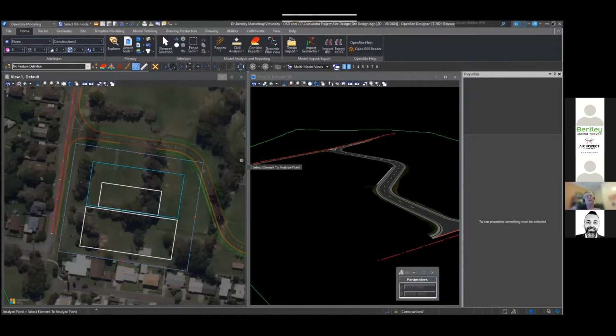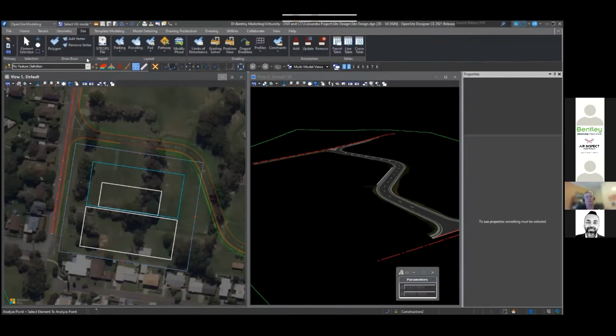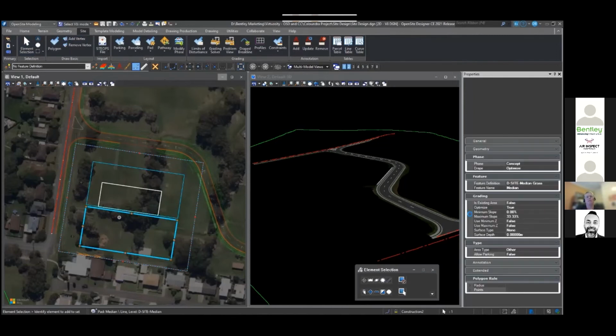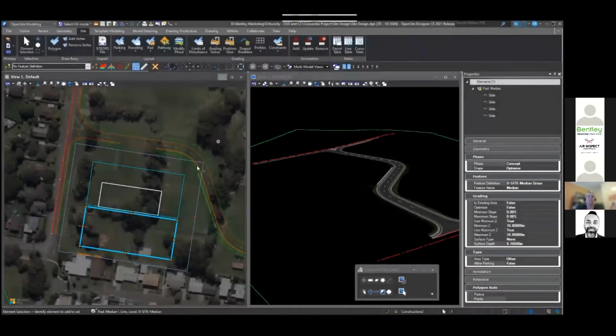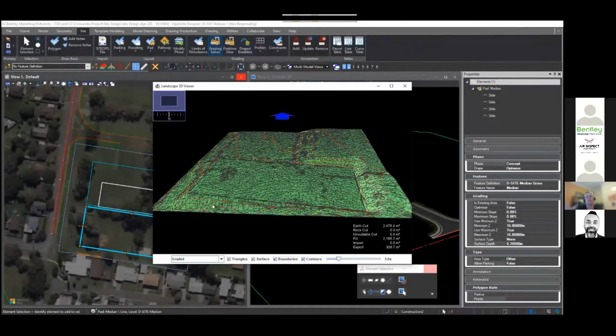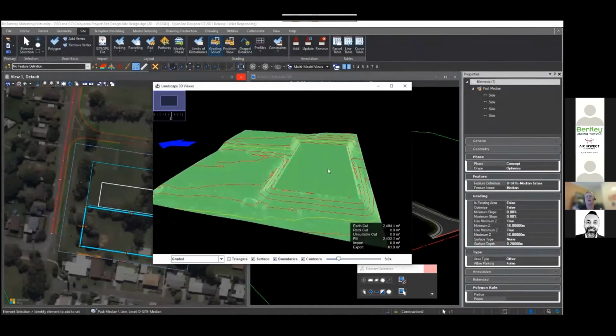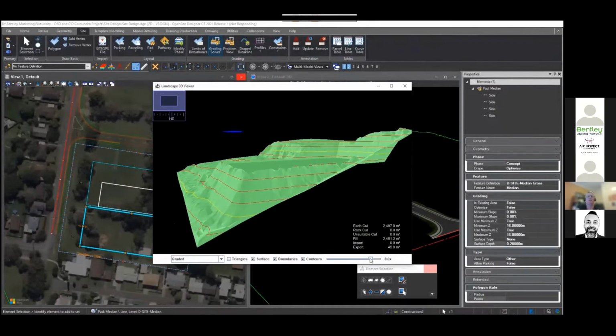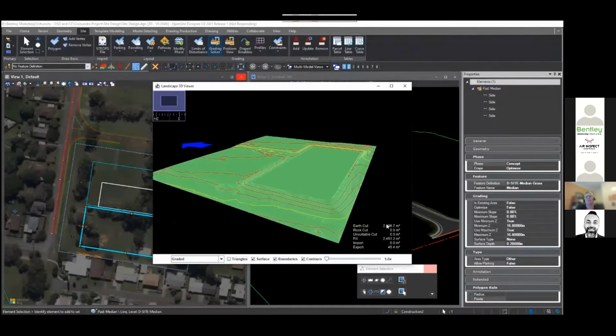So the first thing that I'm going to do is the bowling green. And I'm looking at what the elevation is at roughly the centroid point. So I can set this object to be at that elevation, which is 16.8. Now I'm going to use the optimization engine here. And you might be thinking, why are you going to do that? Because I fixed the elevation at 16.8, and you're right. It really doesn't do much because I've fixed it. I've locked it down at an elevation of 16.8.